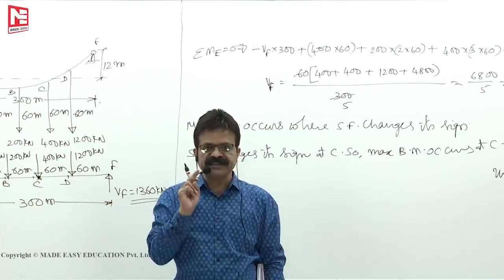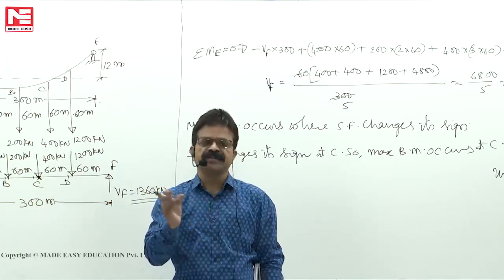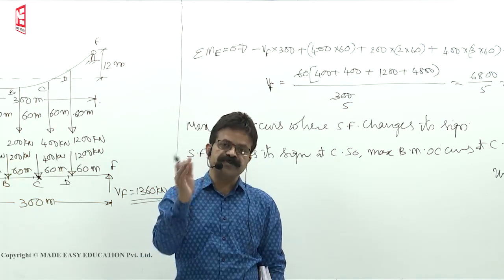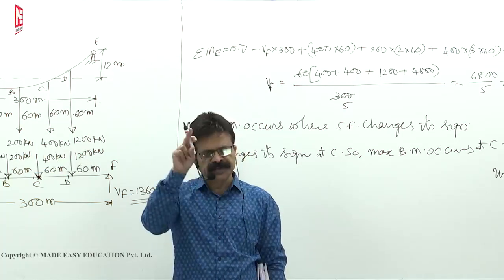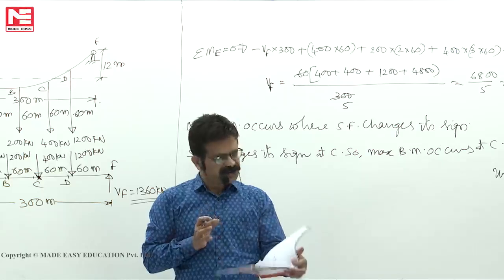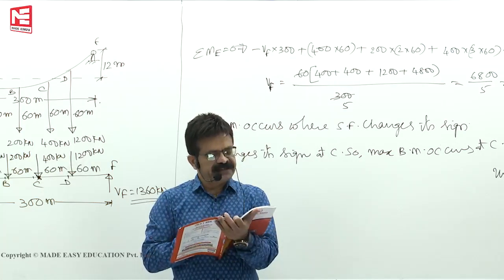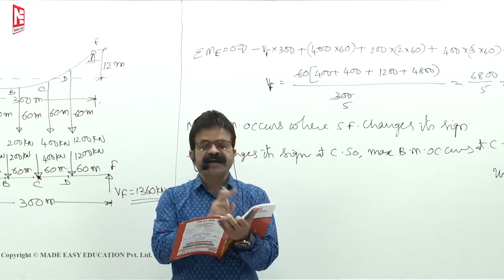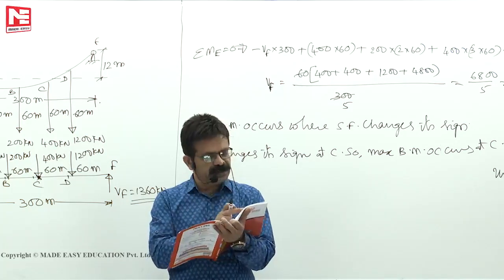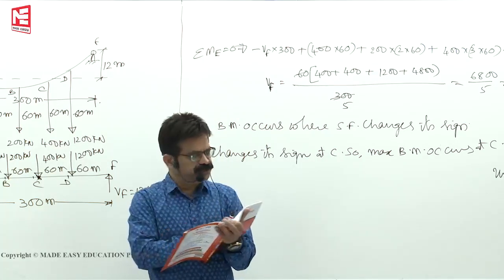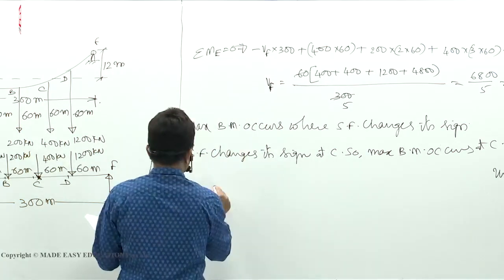But when live load is there, like a point load on some part of the beam, then the hangers will take the majority of the load. That means hanger bars, and only a little amount of reaction will be there at the supports. So this statement is also correct. Stiffening girders in a suspension bridge carry only live load, not the dead load. So which of the above statements are correct? Both 1 and 2. Okay. Sixth question, C.